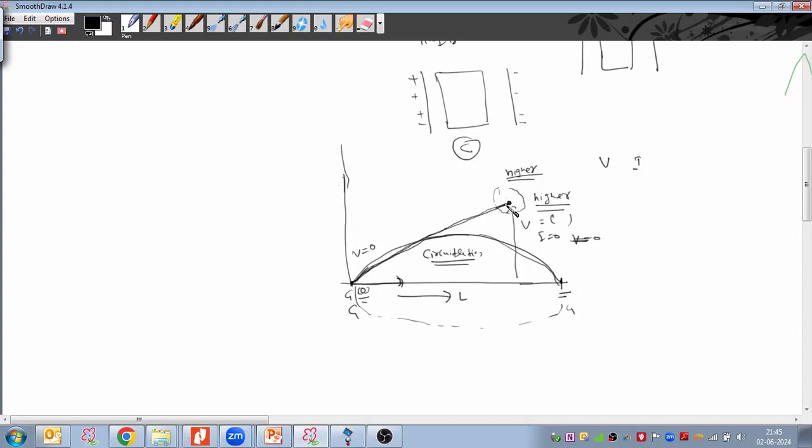If I do direct grounding of the second part of the metal sheath, it will start circulating current. So what I am doing is, I'm not grounding directly here. I'm putting an SVL.